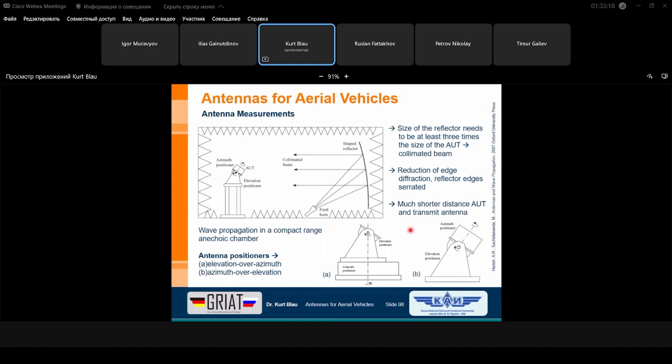Voltage standing wave ratio, VSWR, is 2, and it's the same value in another measurement scaling of 10 dB return loss. So if the antenna works inside between these two values, then we speak about the bandwidth of the antenna.